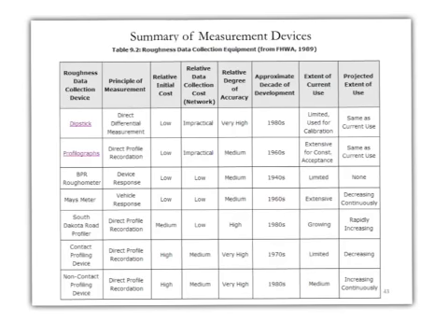So in summary, I tried to put most of the roughness data collection equipment together. This is from a report that was published by FHWA in 1989. It's still applicable. We have several roughness data collection devices, from dipsticks and profilographs all the way to non-contact profiling devices, and the second column includes the major principle of the measurement.